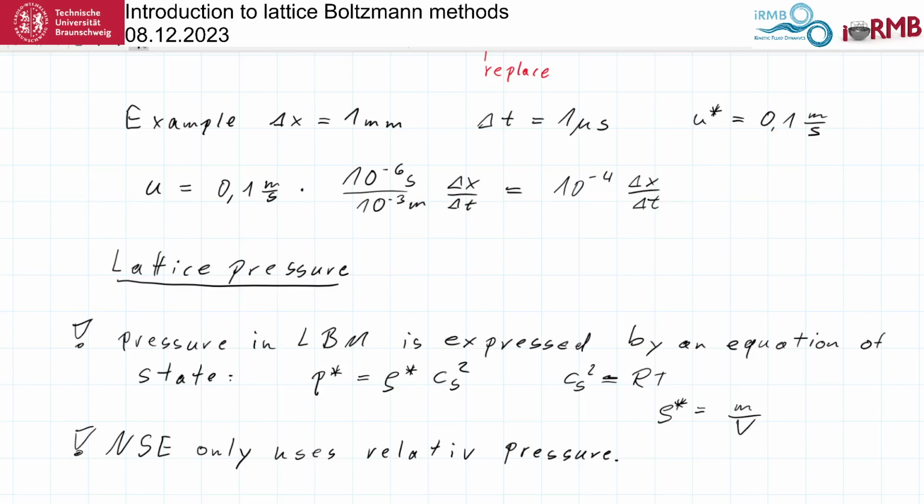In the Navier-Stokes solver, you would probably specify pressure somewhere and set the pressure to 0, right? Because for the Navier-Stokes equation, pressure is a potential, and you set your base potential somewhere arbitrarily. So it makes sense to say there's an outflow and here we put pressure 0, yeah? Just makes sense, because there's no other reason.